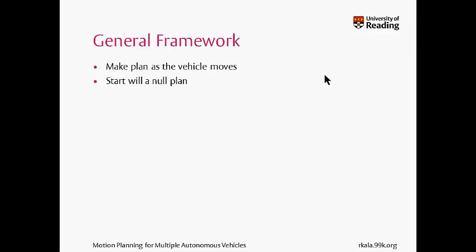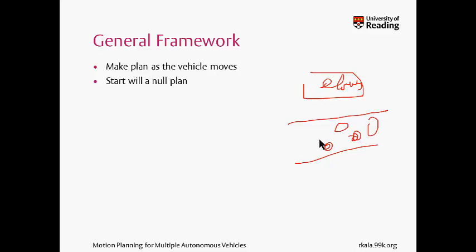So it is a path planning, path correcting, path rectifying algorithm. And what this algorithm does is that my planner keeps a very close look at what's happening in the road scenario. If there are new obstacles, it basically sees the scenario, and this is my vehicle being followed. My planner continuously sees the environment, and whenever there occurs any change, suppose this was the old trajectory, and there happens to be an obstacle like this, it will immediately rectify the plan. So that's what my planner is doing.